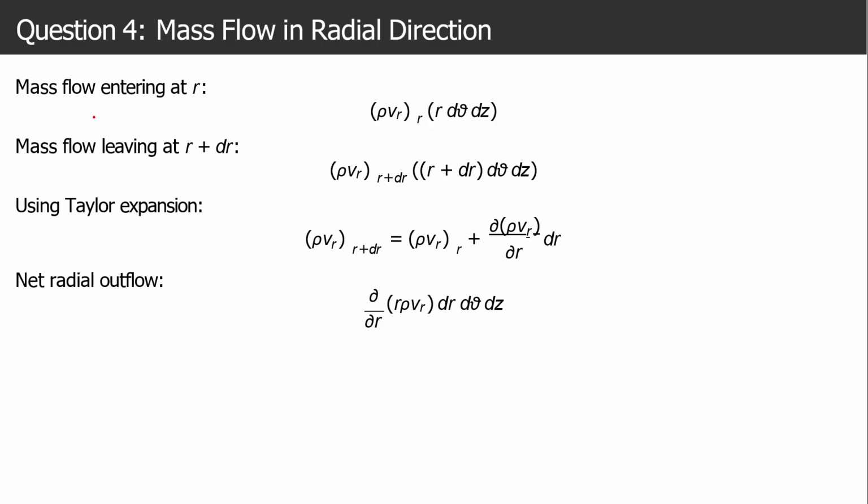So this will be our mass flow rate: rho in kg per meter cubed, v_r in meters per second, and area in meter squared. Cancel out everything, we get kg per second, so it will be mass flow rate only. Just take it like a flux, where the velocity component is going perpendicularly through the perpendicular area. So this is for v_r at r, and this is for v_r at r plus delta r. Now we have these two points, r plus delta r and r.